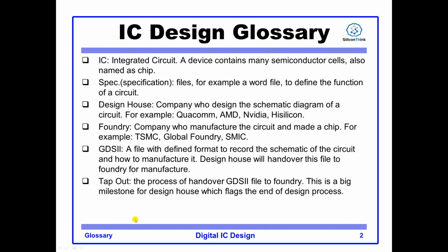Tape out. The process of handing over the GDS2 file from design house to foundry is called tape out. This is a big milestone for the design house.